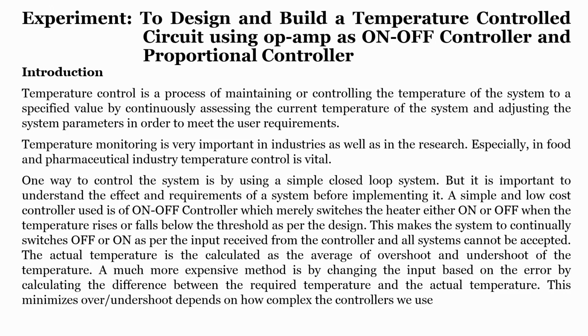The first idea that comes to our mind is to use a simple closed loop system, but it is very important to understand the requirements of a system before we actually implement it. A simple and low cost control is the on off controller, which merely switches the heater either on or off when the temperature rises or falls below the threshold as per the design. So, the easiest way to design is an on off controller.